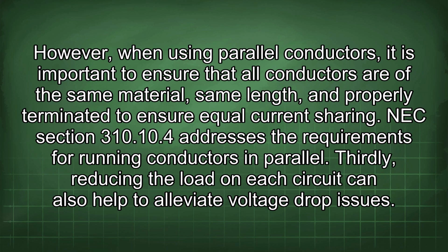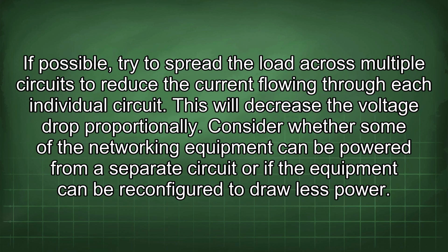Thirdly, reducing the load on each circuit can also help to alleviate voltage drop issues. If possible, try to spread the load across multiple circuits to reduce the current flowing through each individual circuit. This will decrease the voltage drop proportionally. Consider whether some of the networking equipment can be powered from a separate circuit or if the equipment can be reconfigured to draw less power.